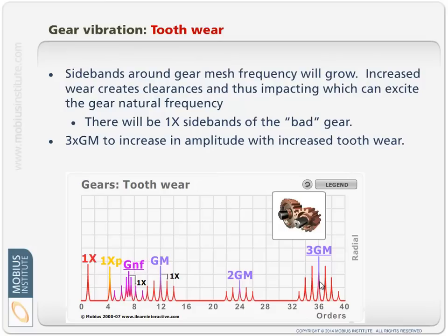So yes, vibration may be an indicator. Ideally you would have already been doing oil analysis, and you should be getting warnings from that technique as well. But every additional piece of supporting information you can get is always helpful when you're making a call like this.